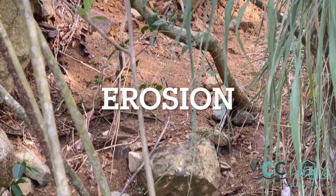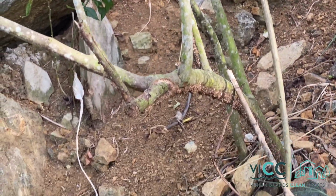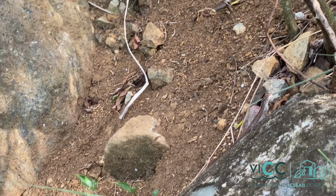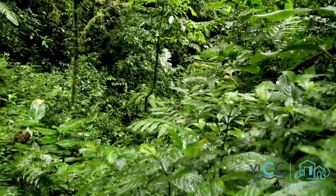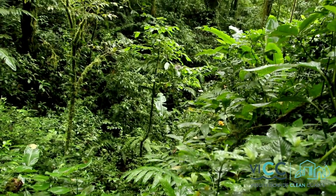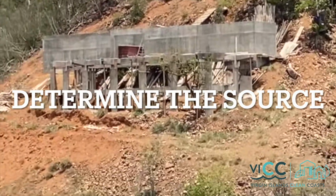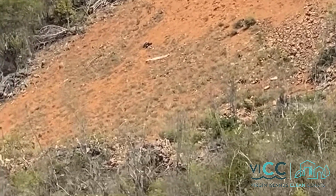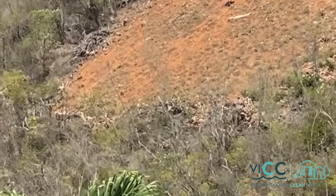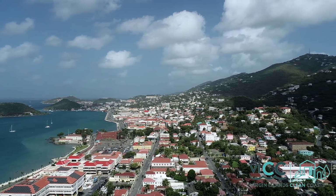What are some strategies for erosion? Erosion is the wearing away of soil and rock and moving it into another location. It negatively impacts water quality, soil health, and plant growth. Use these strategies to address erosion immediately and minimize these effects. Determine the source. Surface water may be entering your property from the road, rooftops, driveways, and even your neighbor's property. Determine the source of the problem to find the best solution.